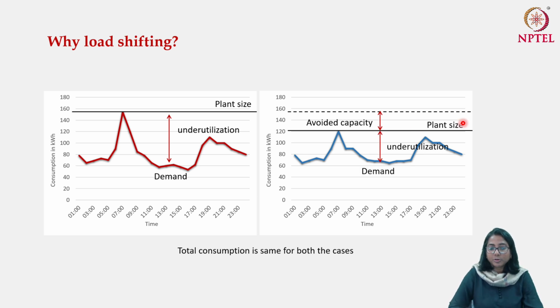During the off-peak period, if you see here, this was the amount of underutilization of the power plant. The underutilization actually comes down because of two reasons. Now your off-peak demand has gone up and your plant size has come down. As a result, there is a squeezing of this particular red line to this particular red line here, which shows a lower underutilization and the higher economic efficiency of your investment. So this is the bottom line of why we want to have a flatter load curve as compared to a load curve which has very deep off-peak demand and very high and sharp peak demand.